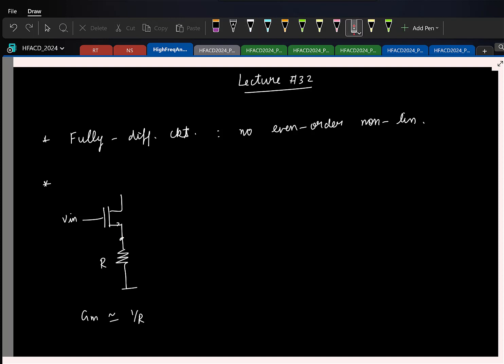And then we saw how to use this and make a differential amplifier. We saw two different variants, and we finally noted that there is an inherent negative feedback happening, because if I increase the gate voltage, initially the drain current tends to increase, but then the source voltage also increases, so the effective VGS drops, and the current also reduces.